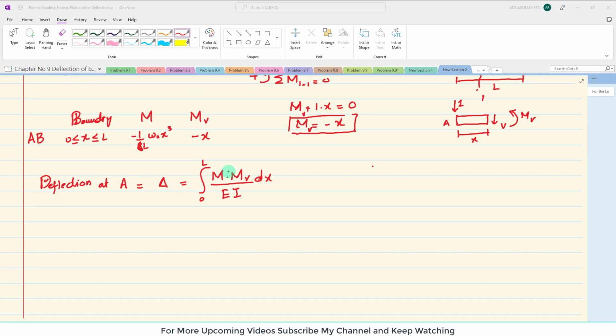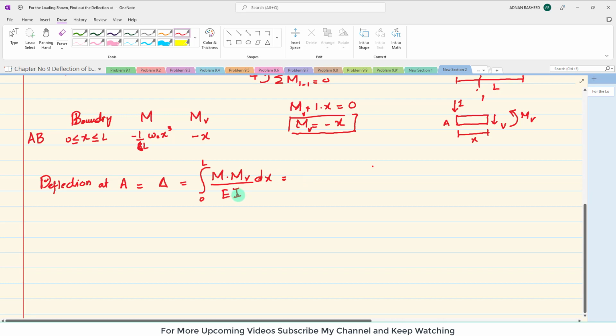You have the values of M and mv. E is constant, so I will take it out: 1 over EI times the integral of M times mv. Now M is minus 1 over 6L W naught x cubed, and this mv is minus x, into dx, with the limits from 0 to L.